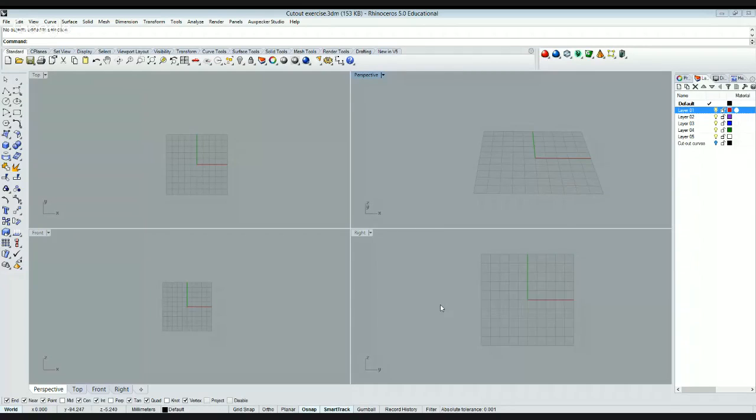So as I said before, we are gonna start by creating the first outer surface. We are gonna start building an auxiliary line in order to start from our first curve. To do this, we are gonna take the command of the polyline, and we are gonna start from 0,0,0. So we type 0, enter, and we have our first point done. If we go to the front viewport, because I want to create a line on the front view, and I want to create a line whose length is 445 units, and its angle from the x-axis is 17 degrees.